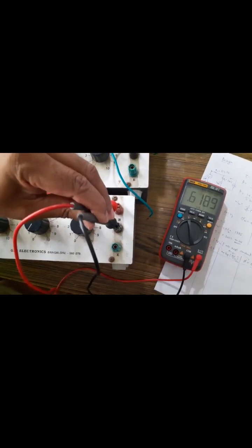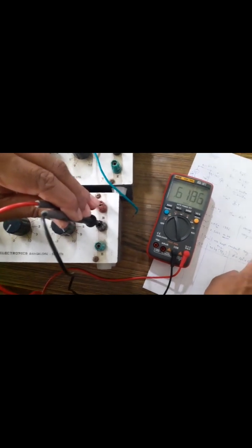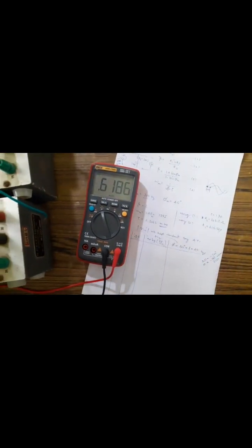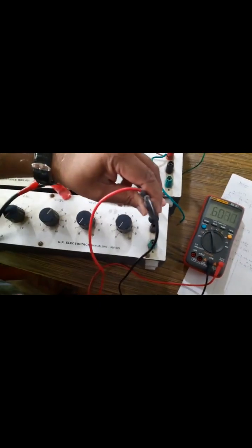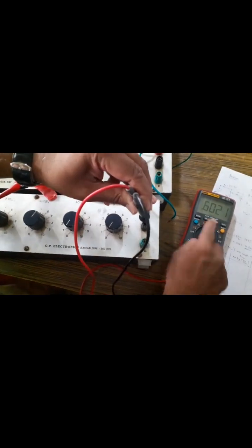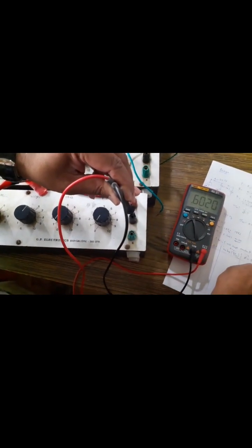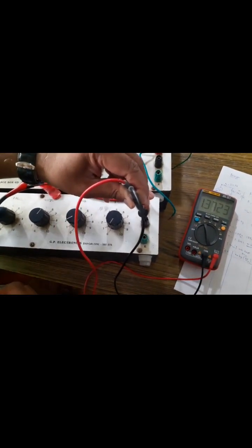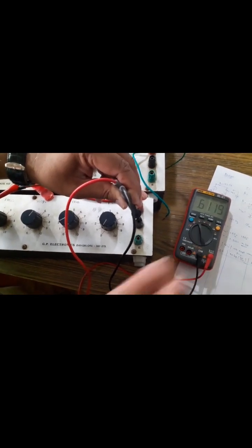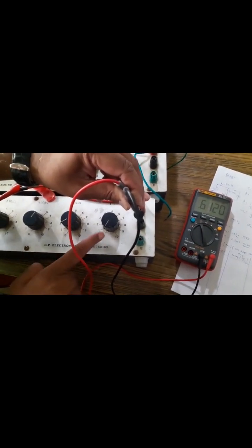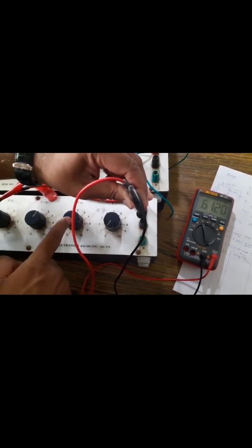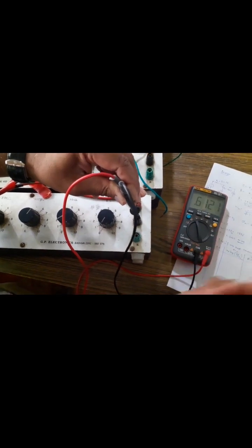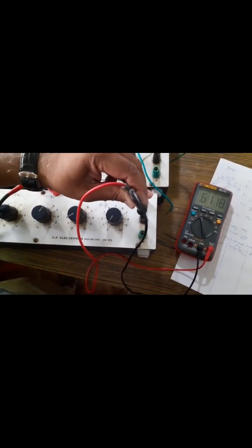Otherwise, you don't get the proper value. So the value should be 612, and if you set it to 6 and make these 0, you are getting 602, but I want 612. Let me increase this one to 10. You are getting exactly 612 now, right? You need not adjust the third knob, because of the tolerance, in fact it is 610, but you are getting 612 which is what we required here. This is enough. Okay, so one decade box setting is over.